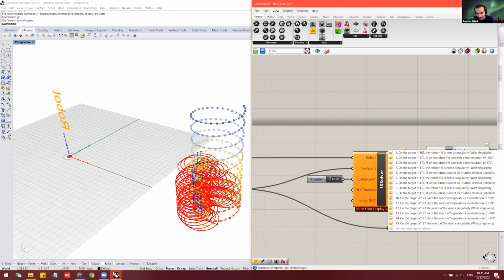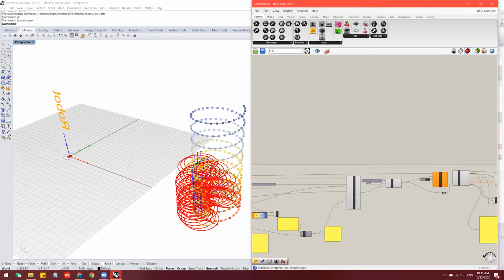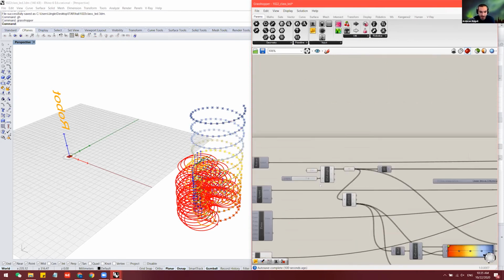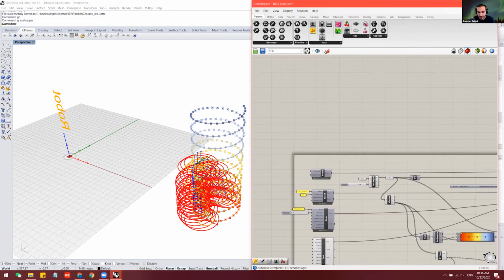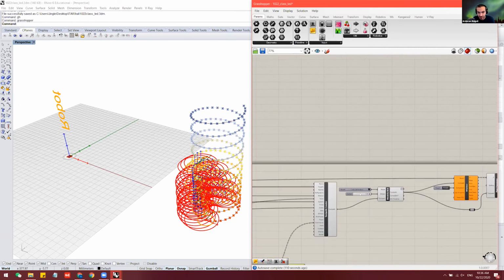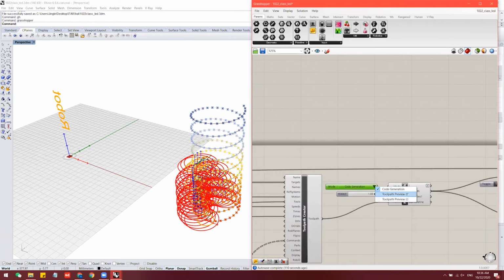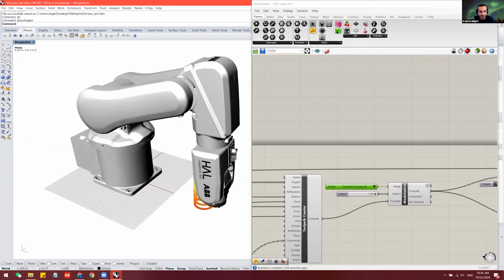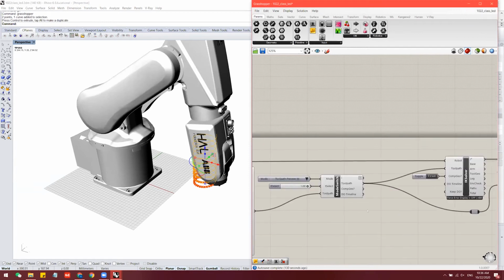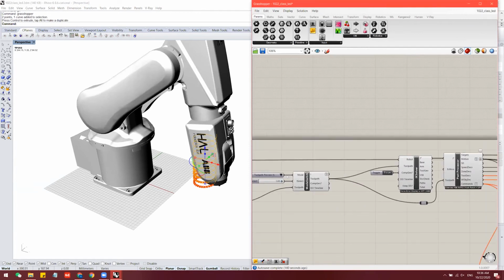And I think the main reason for that one is the fact that those targets are far away from the reachability of the robot. Okay, so can you just get into toolpath preview instead of code generation so I can see what's going on? Yeah. Oh, which one? The T one. So you can actually see the whole path. Okay. So I think those targets are in really bad position for the robot. So I think if you move everything up, it's going to be easier for the robot to reach them. Okay, now go for code generation.